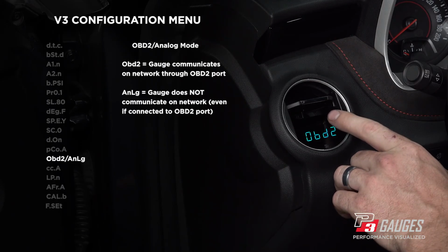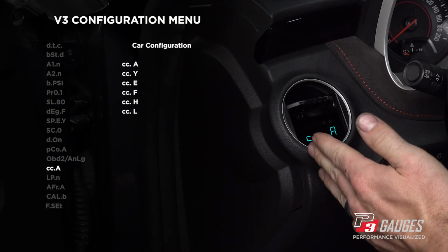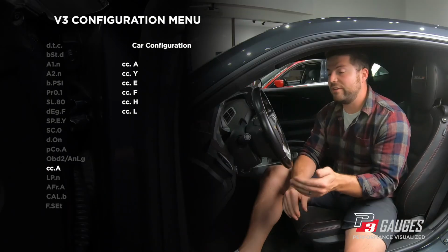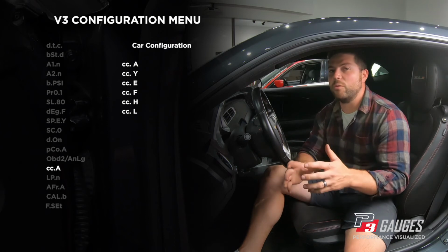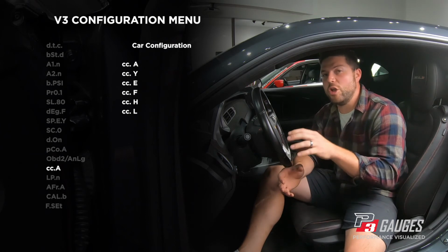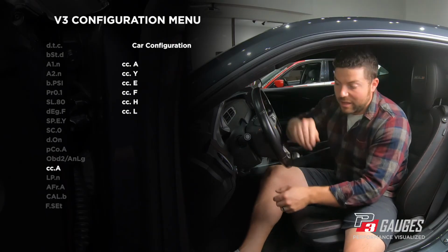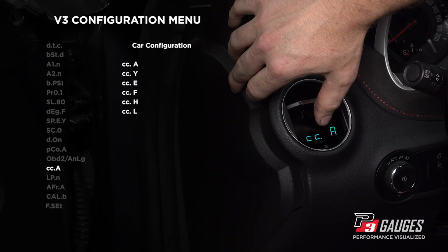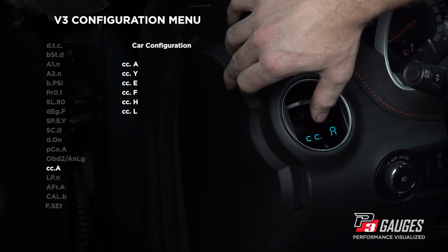We're gonna tap the right button to go to the next setting. This is your CC setting, and we can see it's defaulted to CC.A. CC stands for car configuration, and that basically just tells the gauge what kind of general car it's connected to, and that will help our software know where to look for information in your ECU. It's going to default to A, but there's a lot of different options there. We can cycle through those. There's A, Y, E, F, H, L, and now we're back to A.